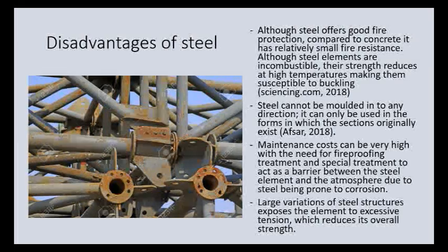Although I mentioned steel has great fire protection properties with added protection from a flame retardant coating, compared to that of concrete it actually has relatively small fire resistance. Although steel elements are incombustible, their strength reduces at high temperatures, making them susceptible to buckling.